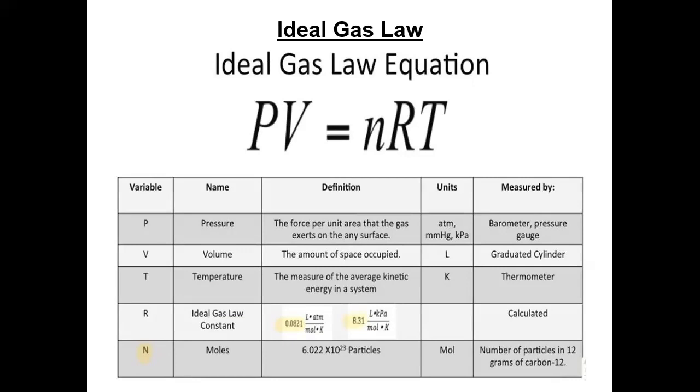We can also work with this in units of mass, where we take the universal gas constant and divide by the molecular weight. We'll show some of that later. And it becomes a specific gas constant, because if you're working with carbon, you take the universal gas constant, divide by 12. And that changes the units from moles to kilograms or pounds or whatever your mass unit is. And then the N turns into an M.